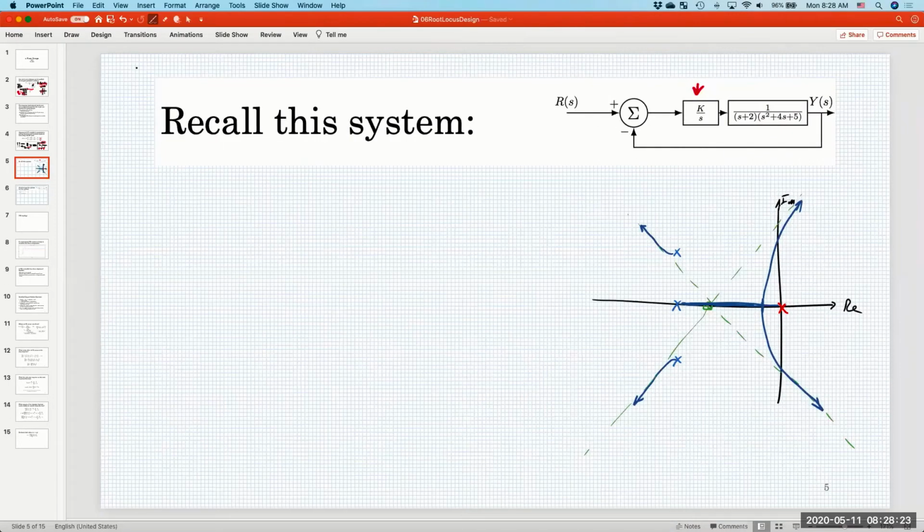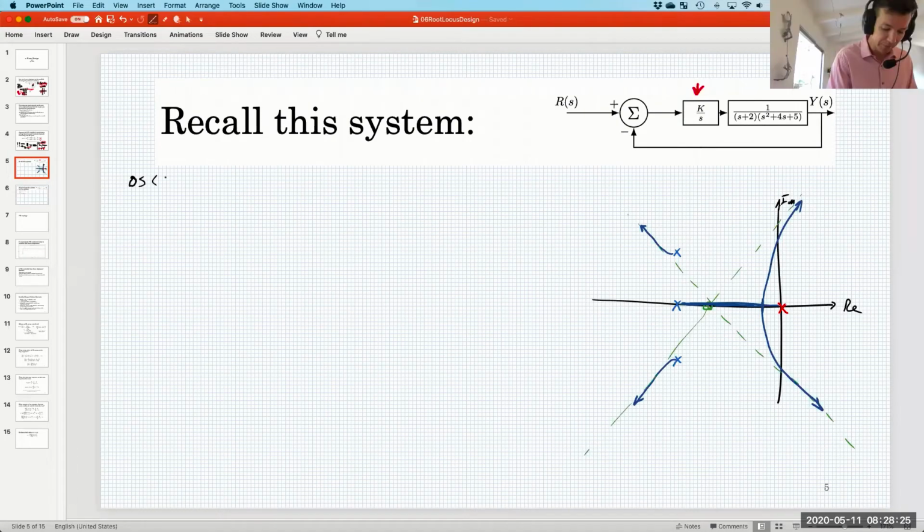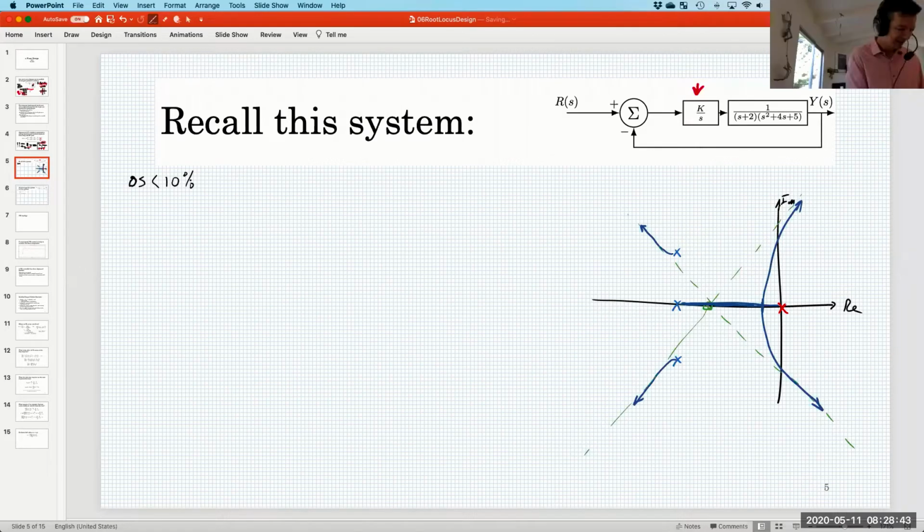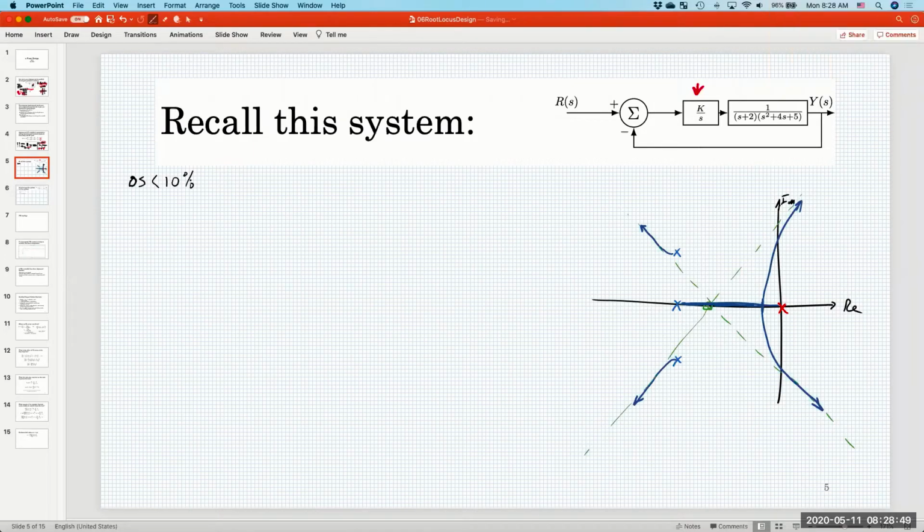Overshoot less than 10%. Okay. Steady state. Hold on. That's a transient requirement, not a steady state requirement. I mean, that's fine. That's what I was asking for. But when you close that sentence with steady state, it confused me. Okay, my bad. How would I say it differently? I think you meant that in response to a step, there's no more than 10% overshoot. Oh, okay, got it. Is that what you meant? Yeah. Okay, sweet.